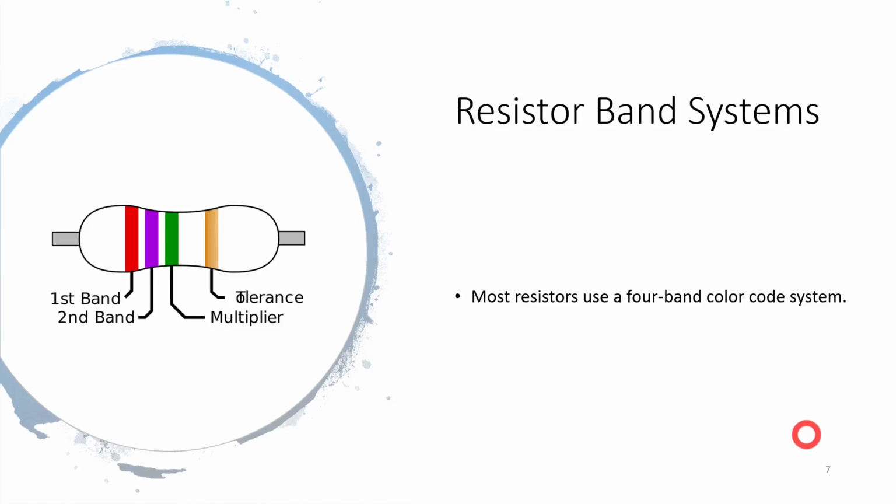That is probably coming out of vogue a little bit, and maybe 5-band resistors are getting a little more popular since manufacturing practices have drawn the costs down. The higher precision resistors are getting cheaper, plus all of our solid state devices that we purchase require tighter balances on all of those things. Precision resistors do have 5 bands on them, and they have their own color code system. The color numbers stay the same. It's just the code and how you read it is a little bit different.